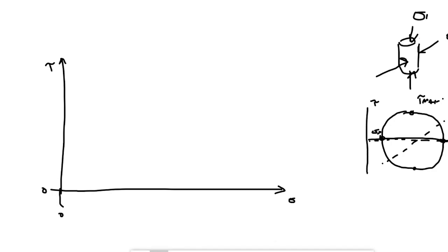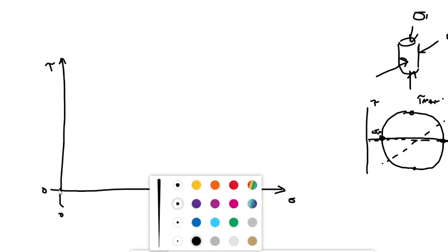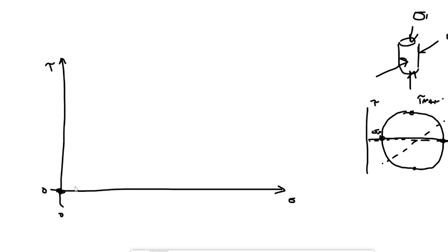So let's just start drawing, and hopefully it'll start clicking. Oh, and you'll notice I'm just doing one quadrant here. It keeps it a little bit cleaner. We don't need to show the reflected, the symmetrical portion below the x-axis, and we'll say that everything's in compression, which is positive in rock mechanics, so we won't concern ourselves with what's to the left of the tau axis either. So to start off drawing these, we'll say that we have this point here. This is the very first test that we ran, where we were in uniaxial compression, where we said that sigma 3, the confinement, was 0, right?